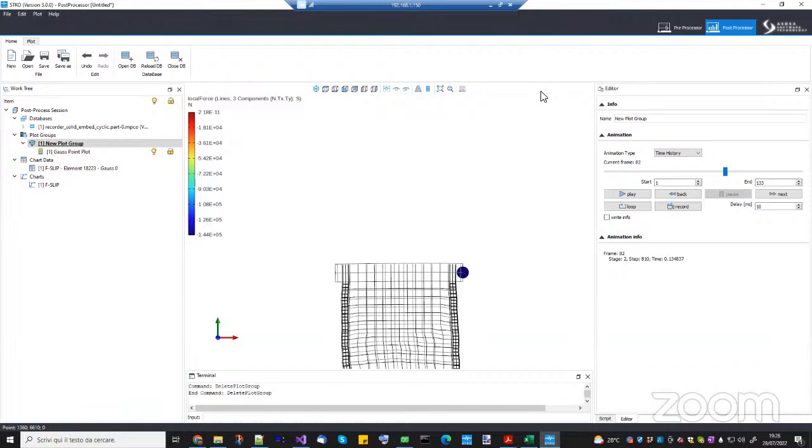For example, here you can introduce bar slip, while it was not possible in the smearing approach, as we did yesterday. Something else available in this model is that since the rebars are made of beam elements, you can directly model the dowel effect, while it was not possible in the smeared layer approach.